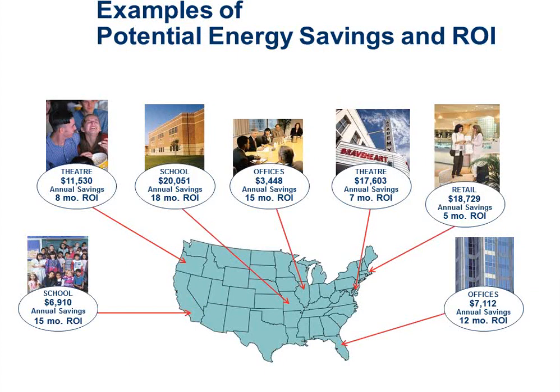Here's some sample savings around the country. Just to give you an idea, paybacks are usually pretty quick. The more densely occupied the space is, the faster the payback is going to be, and the more volatile the head count is. So the more people that are in the building today but not there tomorrow, or there this hour, not there the next hour, the more volatile the head count is, the more often CO2 is going to pay for itself.